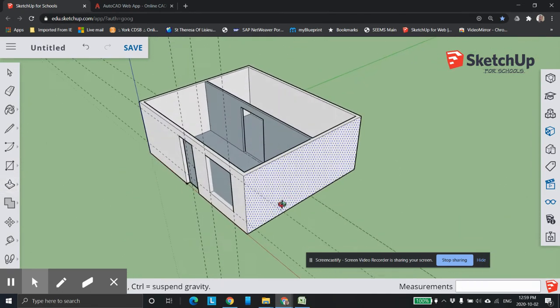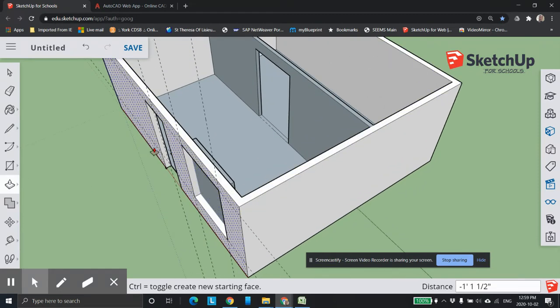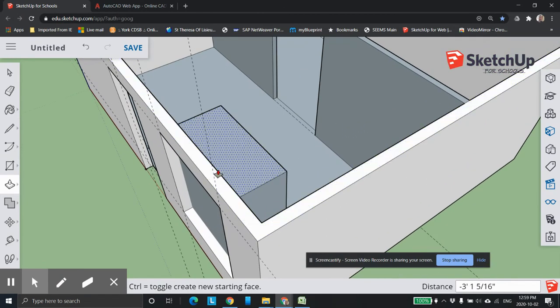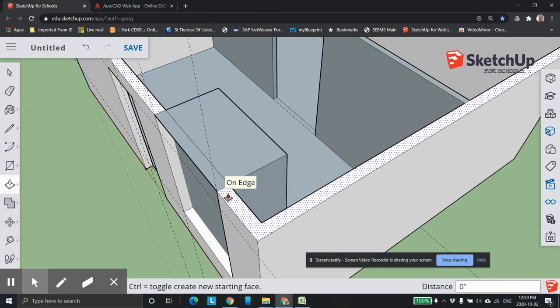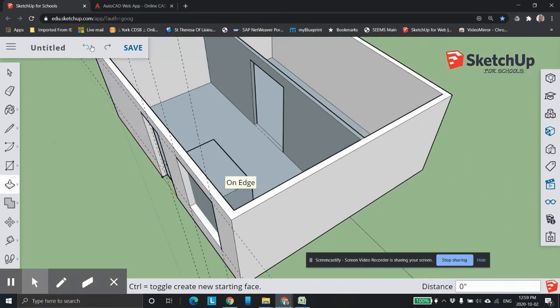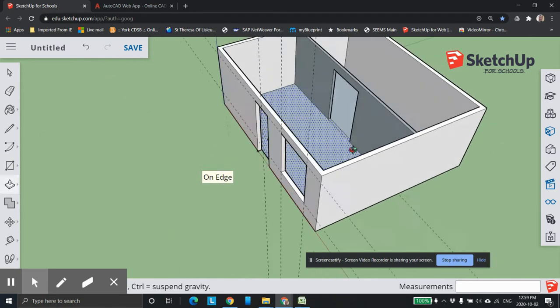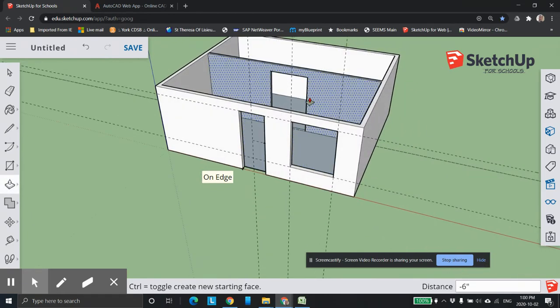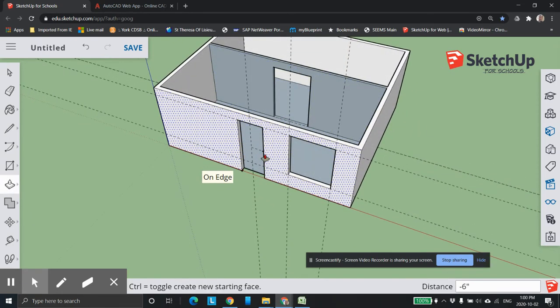Cut it. Nope, see, you dragged it in. That's what I was referring to earlier. So if that happens, and you're walking it through this way and it's building something like that, just click this edge, zoom in here and click this edge. Oh, try that again. Click it and bring it through, and just touch that edge right there. See where it says on edge, and you click it, and it'll cut the window out. So there's a window out. We've got the interior wall done, and I found this method much easier.